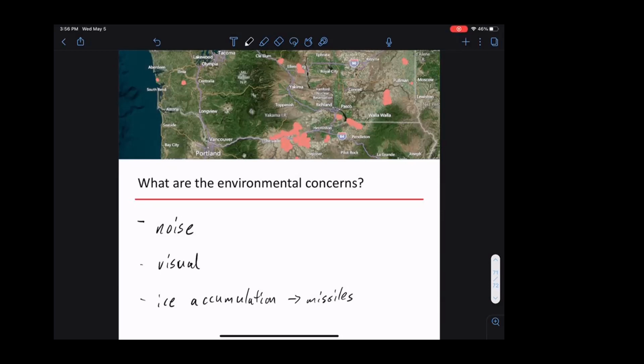So how do you link something going at 60 RPM to a grid that goes at 3,600 RPM? That is also part of the engineering questions, how you engineer this generator. We'll get to this when we talk about synchronous generators, and how a relatively slow mechanical rotation speed connects to a grid that's pretty fast.